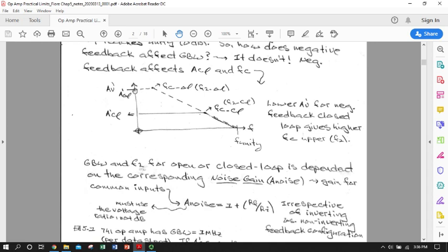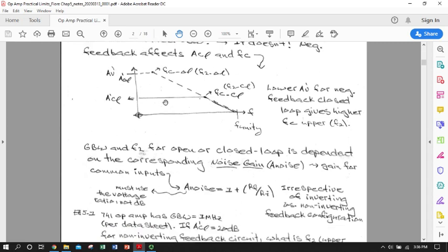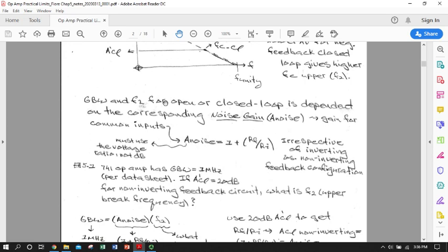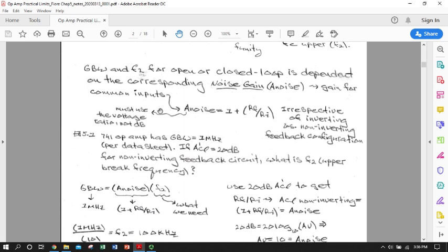It's also called the upper break frequency, and that's where your flat line breaks. It has a slope break or a slope change. And you'll see that in our textbook, you'll see that some in my notes, and you'll see it in other articles and tutorials and possibly in spec sheets. So upper critical, F sub 2, and upper break frequencies all refer to the same thing.